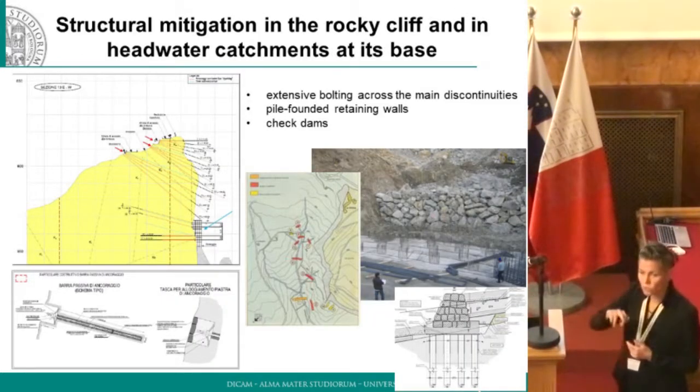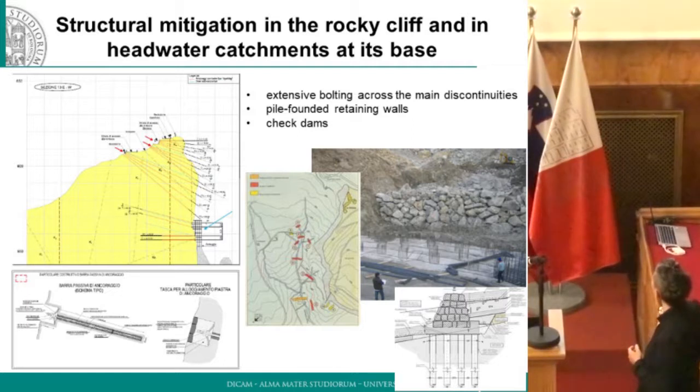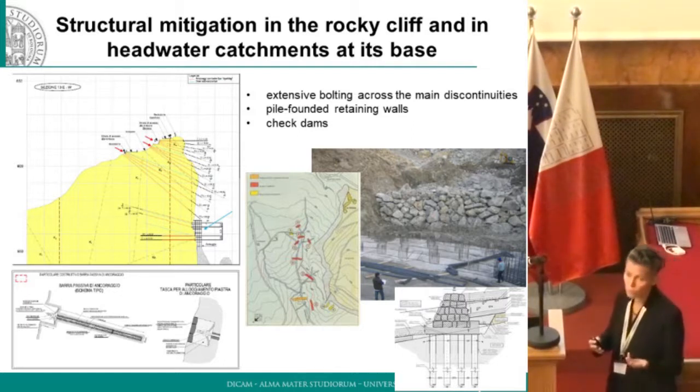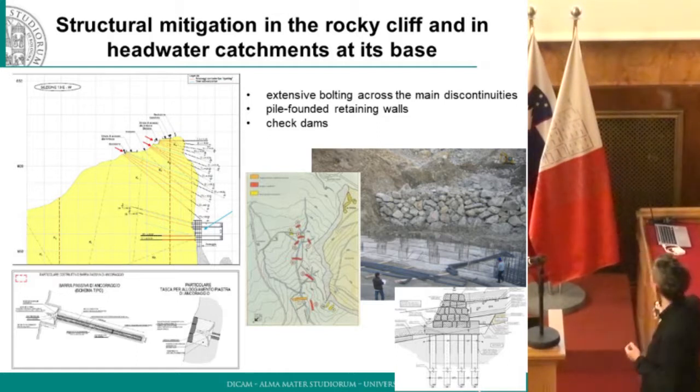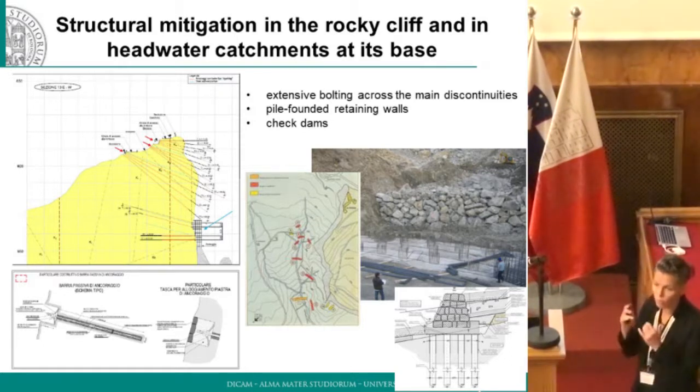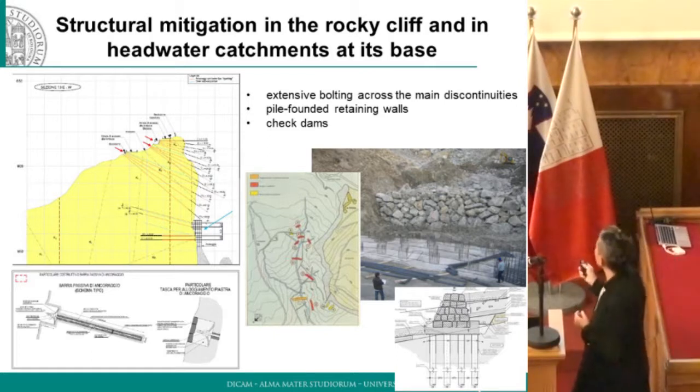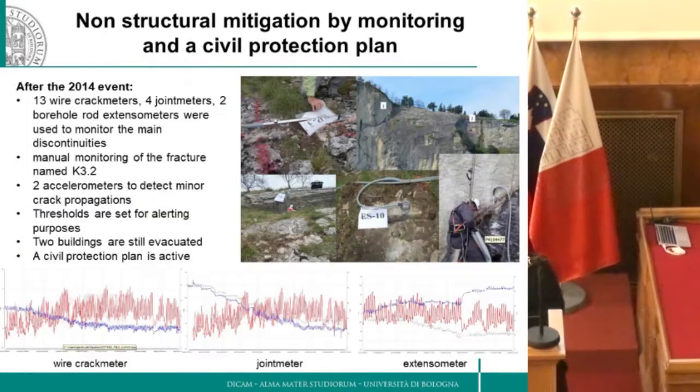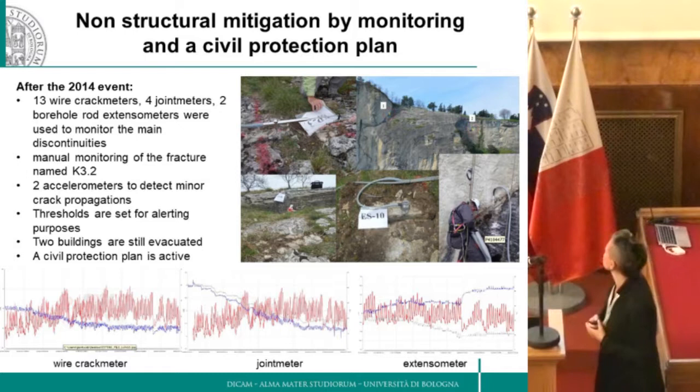So we have this circle of processes. We have groundwater flow in the slab. We have chemical and physical processes which are promoting weathering at the base in the clay shales. And then you have undermining of the slab. After this, you have the development of tensile stresses in the upper part, and then the onset of large-scale slope instability. So from slow processes, you end up with rapid processes. And this is a circle. So this happens in a sort of circular process.